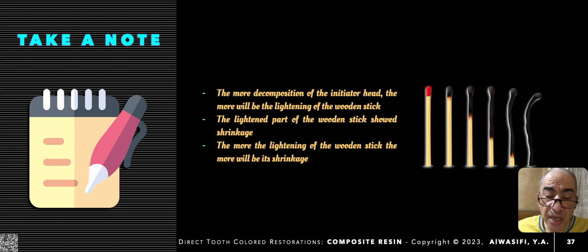Polymerization shrinkage is an important positive criterion for your polymerization reaction. That is to say, when you get maximum polymerization shrinkage, it means that you maximally cross-link your polymer chains, and the material will get the best mechanical and physical properties in terms of strength, modulus of elasticity and stiffness, and all mechanical properties are improved.